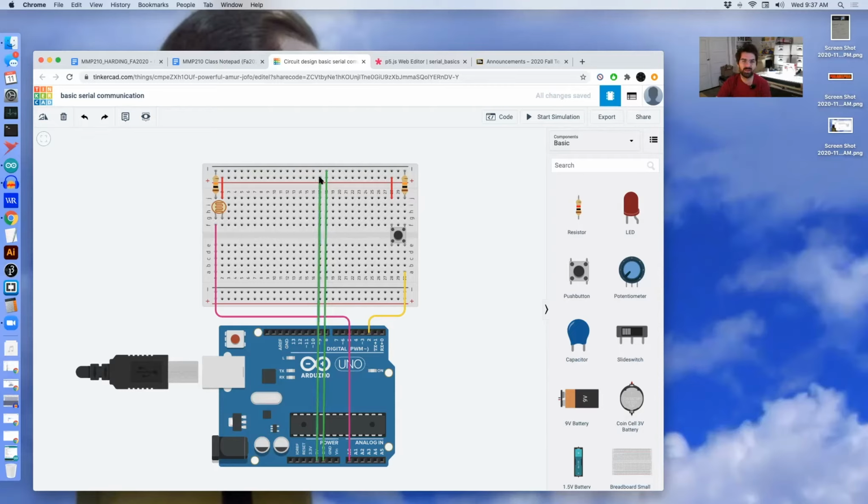And then we have this other wire, which is connected in our breadboard to all of these pins. That's going through this wire to our 5-volt pin on the Arduino. So following our 5-volt connection, we have our wire going into the breadboard here, and it goes to both of these red wires, which then in turn are connected through the breadboard to the other side of our button and to one side of our photoresistor.